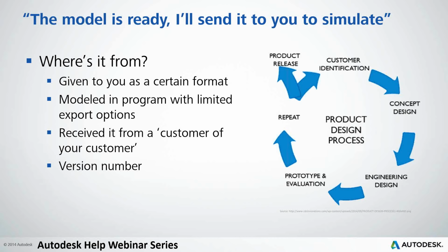If you notice that you get through an analysis and all of a sudden you realize that, oh, it's a different geometry from what they're using at the actual tool being cut, then that could be a big problem in the end. So keep going back, checking that version number, checking to make sure all the features align with your tool or with the part design, and that'll really help you in the long run.